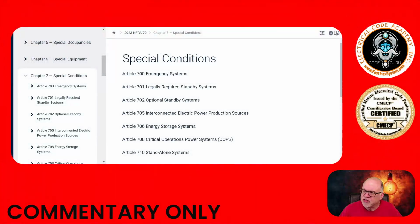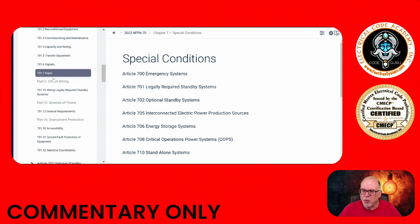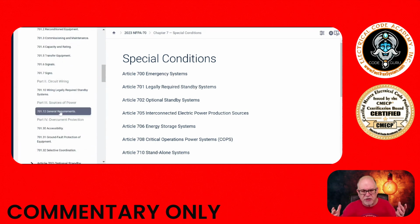So here we are, Chapter 7, special conditions, and you see there is the emergency systems, Article 700. Article 701 is the legally required. That's where we're going to be. And then you have the optional. So those are your three different types of standby systems, okay? In your legally required, we know that what we're talking about is a general requirement. It's about the time factor, okay?